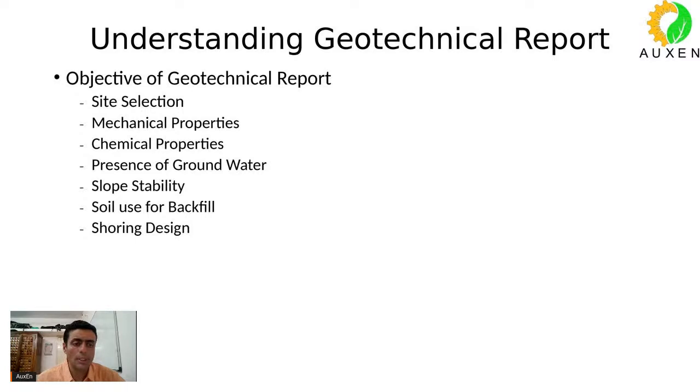The next very important objective of doing a geotechnical investigation is to understand the presence of groundwater. Extremely important. I have personally seen many projects having trouble or running into problems because the groundwater was not adequately or properly tested. So the presence of groundwater is very, very important, and a good geotechnical report will always try to find out the presence of groundwater, its level, and the chemical properties of your